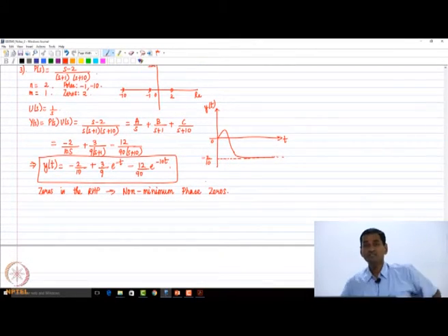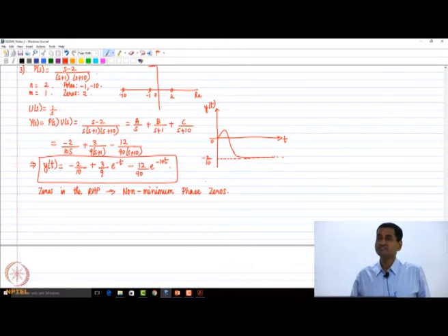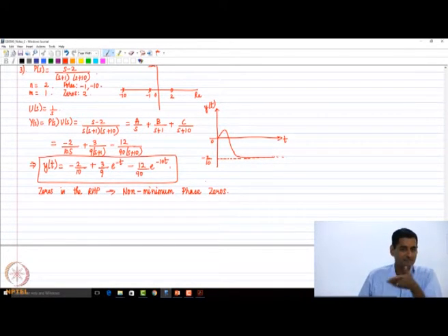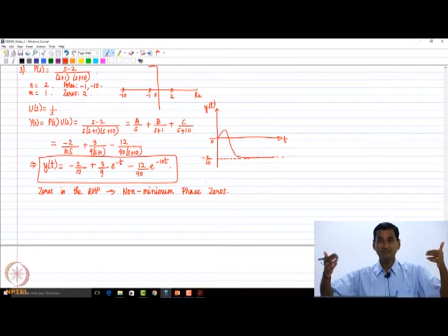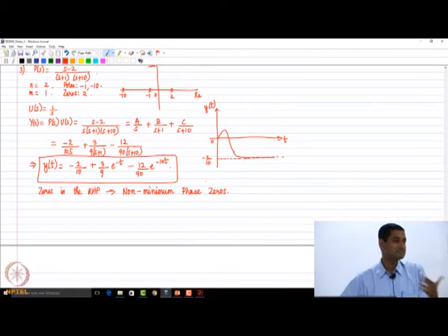Now the question is, when do we get a non-minimum phase system in practice? I have to give you an example. If you leave the system design to me, I would obviously never put a 0 on the right half plane, due to this limitation. But can I get a 0 in the right half plane by the system's characteristics itself, which is given to me?